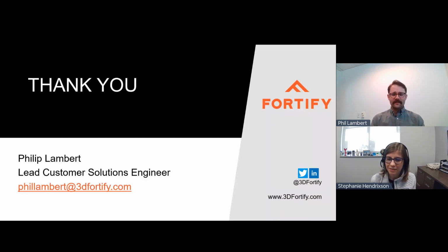Okay. Yeah. So the GRIN devices are a great example of that, right? The gradient refractive index is driven by localized density of the 3D printed material. When you want to control local density in a lattice, you control it by controlling the wall thickness or the strut thickness of that lattice. So in one of our primary application spaces that we're focusing on and doing a lot of development on, we intentionally leverage a gradient of density by leveraging a gradient of wall thickness from the center of a lens to the surface of a lens. So we can physically introduce these gradient structures through geometry control, through how we expose our UV light into every layer.